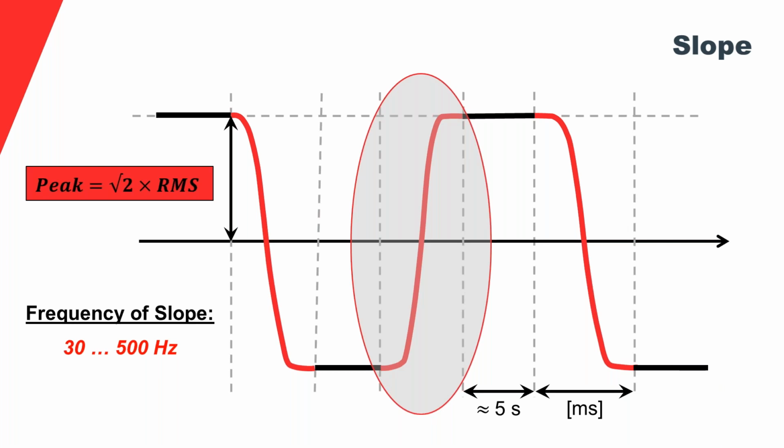Why is that important? Why does VLF have to be seen as RMS? Because the growth of the electrical trees is a function of the frequency, that's well known, but mainly a function of the energy. And the energy you pump into a system is directly related to the RMS.